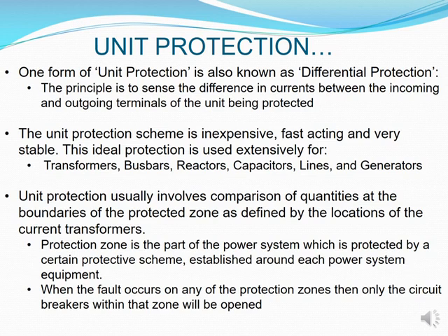One of the unit protections that we are very aware of is what is sometimes referred to as differential protection. That really looks at your incoming versus your outgoing in any system or circuit. All that you want is that the same current that went in would be the same that comes out of that system. So that's what your differential protection really looks at.